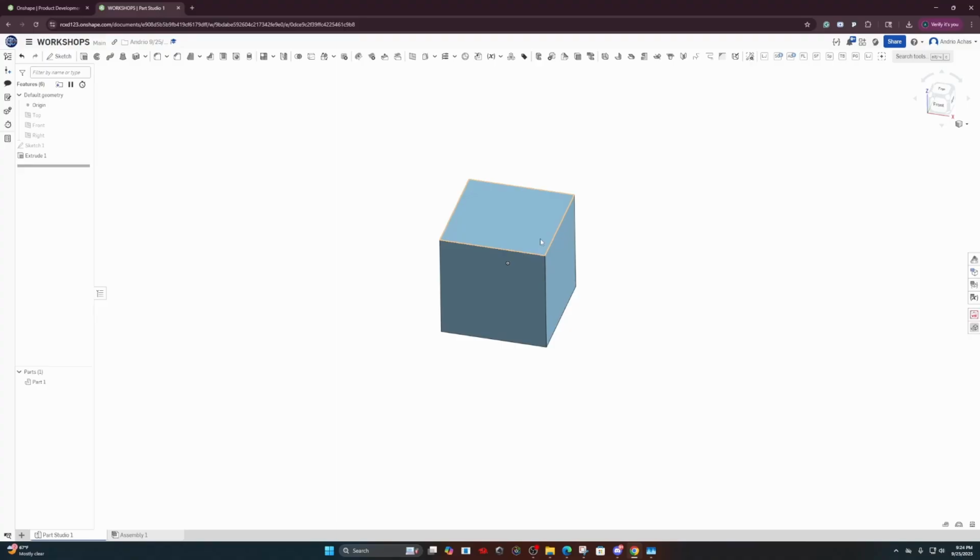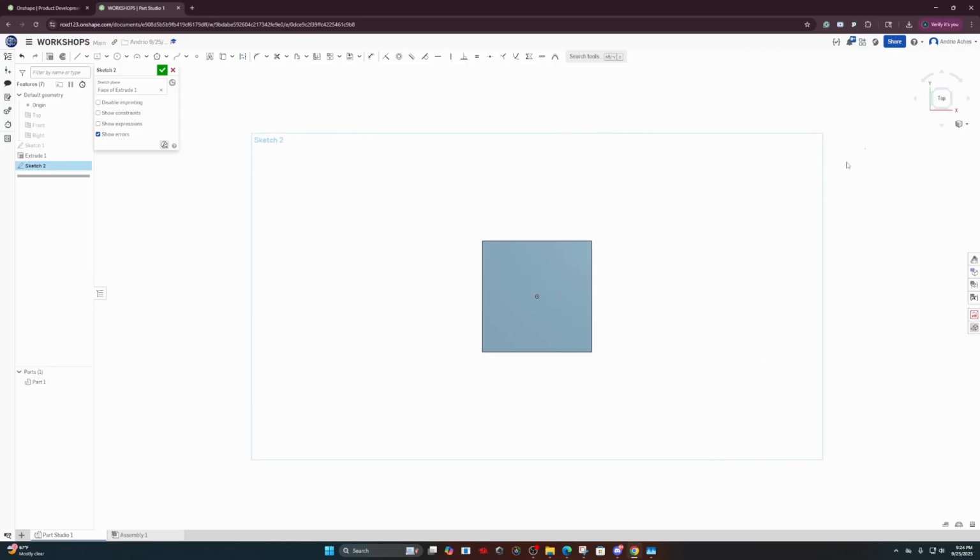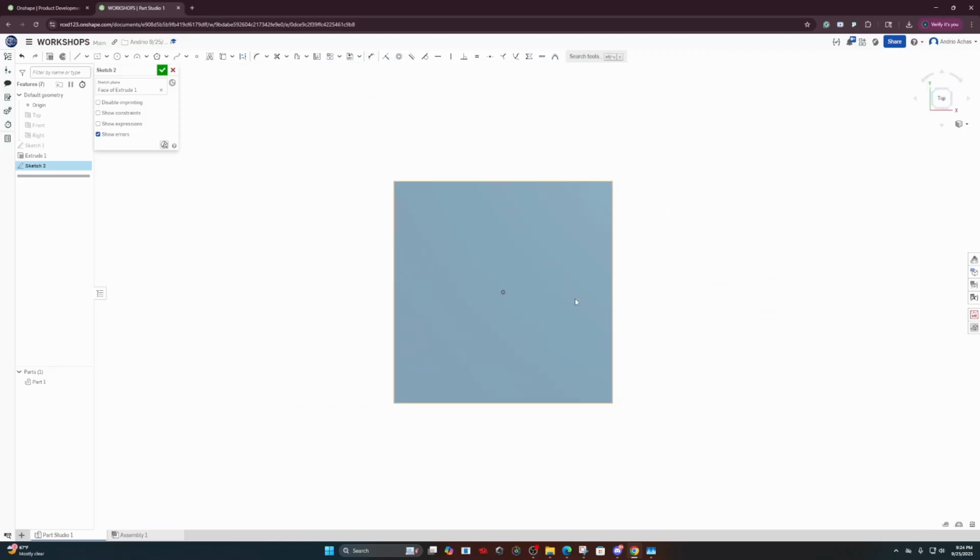So let's just try giving this guy a hat. As you can see from what I said earlier about sketching, you can either do it from a plane or a flat surface. Since this is a cube, this is a flat surface. So just press on that flat surface on the top. Press N or the cube right there. And let's give this guy a tiny hat. Let's try to make this hat straight in the middle. Ta-da! Using the center rectangle. And let's make this hat 0.75 inches.